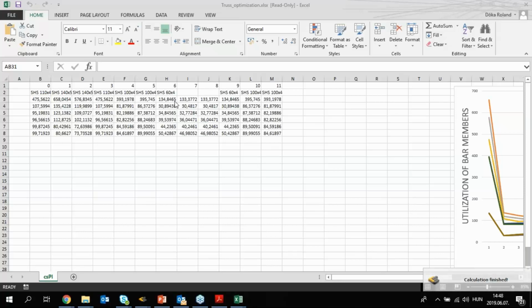Okay, we have one question received. Is it possible to optimize members for local deflection check with the current functions you have developed? Well, you can get results from the analysis, deformation results also, and based on these results you can make certain changes on your model. So you can do that if you write a script for that. Yeah, you can do that. There is a way to do that. The functions are available to do that, but you have to write the whole script.